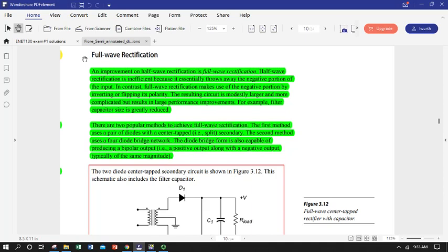And we looked at using the tau time constant of our capacitor load circuit to gauge what size capacitor we needed. And we explored the difference, based on the size of our load resistor and capacitor, of our true DC and our ripple, our remaining periodic signal superimposed on our DC. And we admitted that there were some limitations. No matter how large of a capacitor we used, it seemed that we always had a bit of ripple. Well, one way to make the ripple smaller and get us closer to true DC is to stop throwing away half of our input waveform.